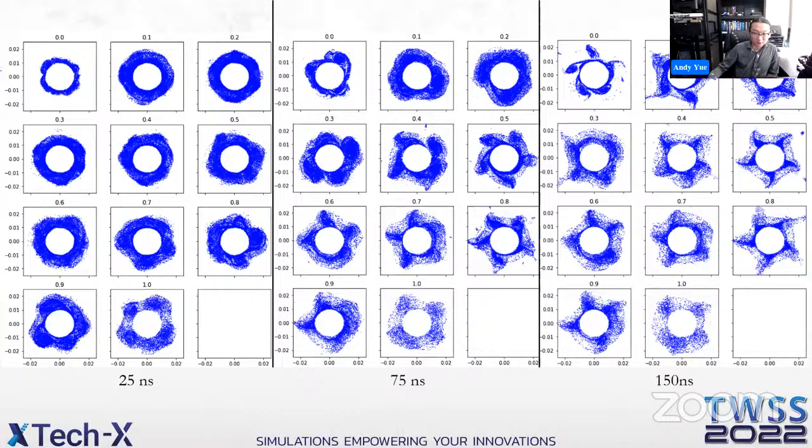Now the level of cycloidalness can be altered by changing the percentage of electrons that are counter-injected. The ratio of counter-injection was swept from 0 to 1 in 0.1 increments. This type of analysis is where the parameter sweep comes in very handy when you need to run a massive amount of simulations. So in this case, I ran 11 cases in total.